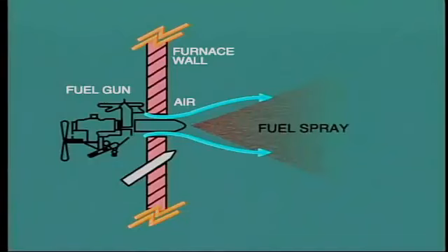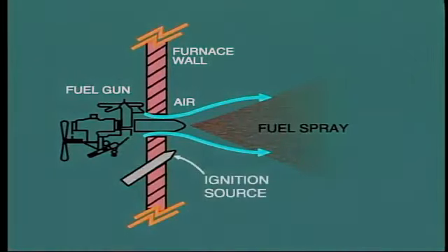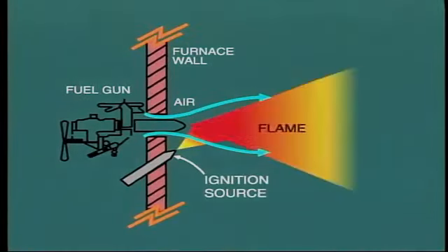In order to provoke combustion, some form of ignition must be provided, usually in the form of a pilot flame or an electric arc. Once the fuel and air mixture start to combust, the ignition becomes self-sustaining and no further help is required. The second item, turbulence, is extremely important.